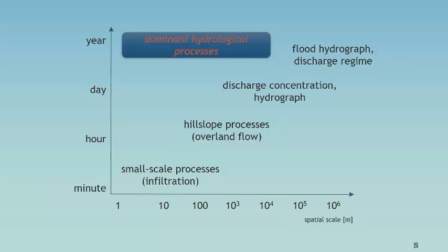A lot of the models are quite capable of handling many different time scales, but sometimes they lack the spatial scale. So SWAT falls somewhere in the day and monthly or annual scale, and we do have hourly scale for certain processes, not all the processes in the model, especially hydrology and sediment, which can be simulated at the hourly scale. So this gives you an opportunity to see where each model may fit in. I can easily put each model name in this graph to give a reference on exactly what model may be appropriate at what scale in both space and time.